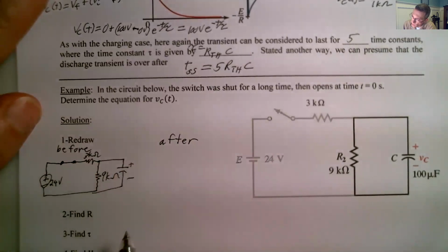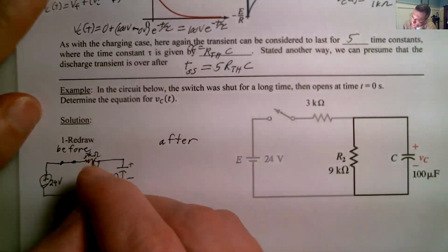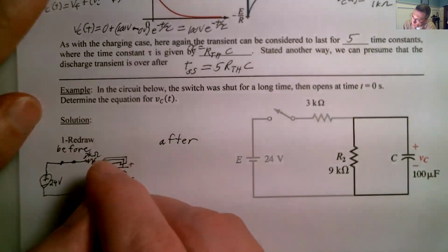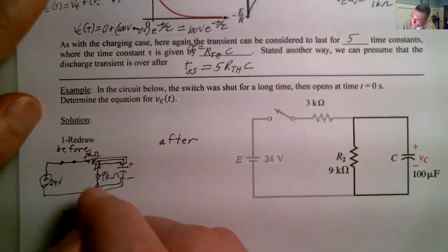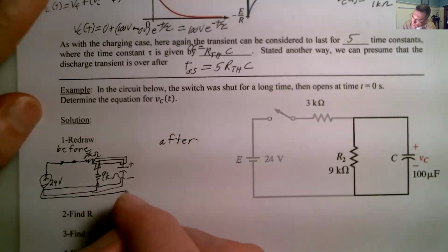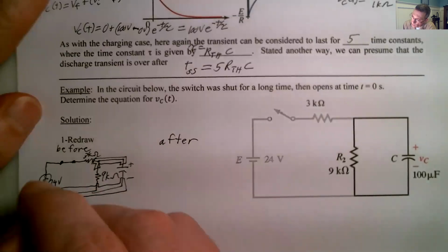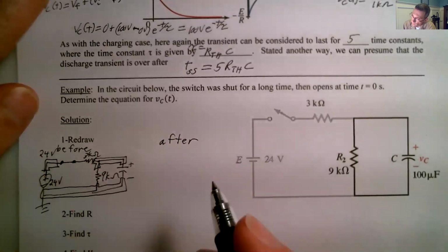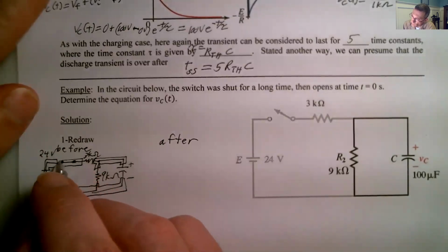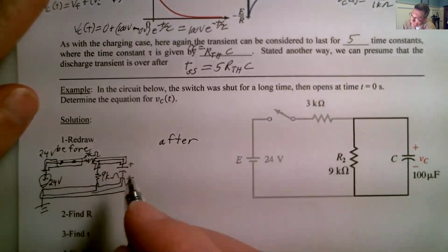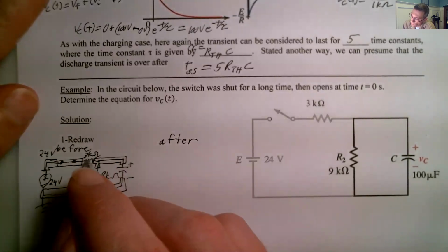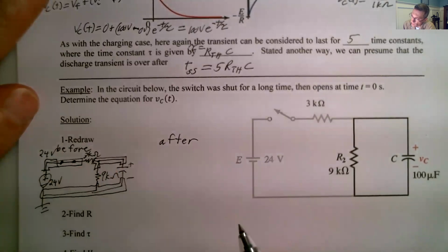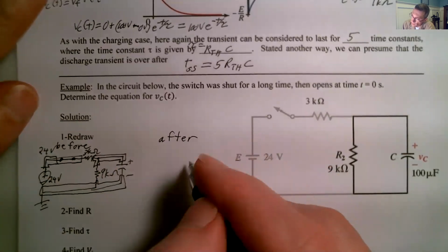The voltage across this, so that's essentially one node. That's a second node, and we'll say ground is there. And this is 24 volts, okay? It goes all the way over. So 24 volts, this is at 0 volts, but there's no current going that way, all right?